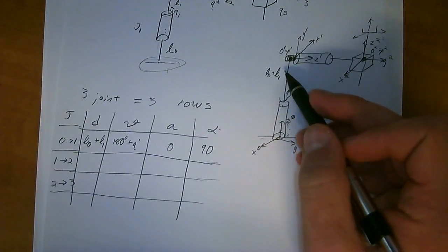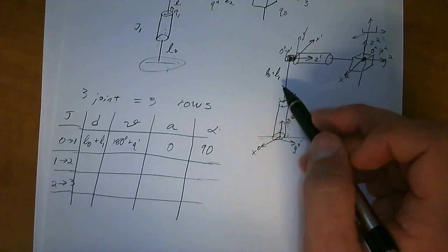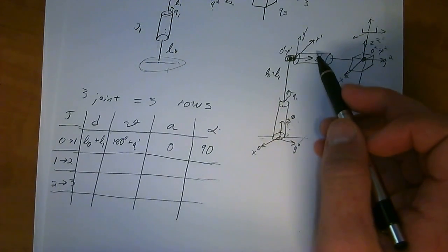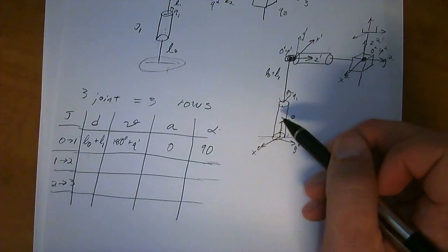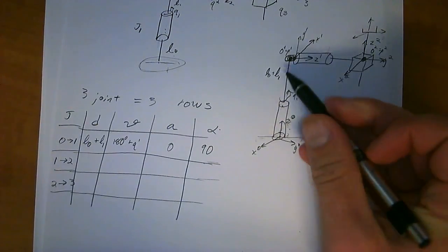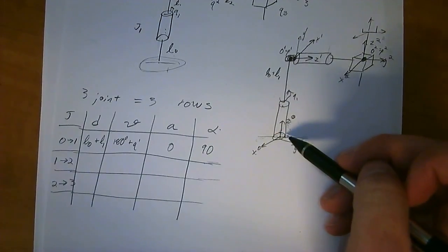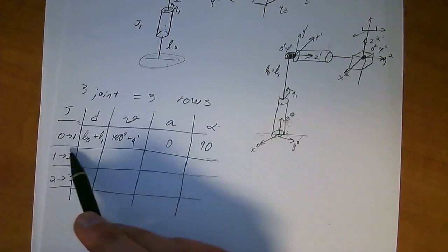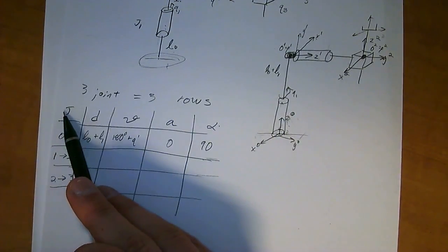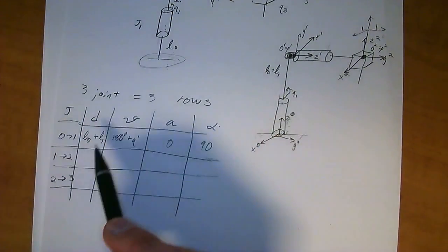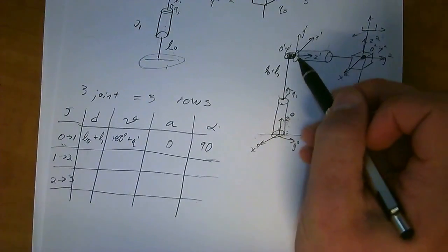We can include this joint in the application. Whereas in the previous forward kinematics that you may have learned, you usually do the second joint in the sequence. Like you go from here to here in the old style, but with DH you go from the bottom of this joint to the beginning of the next joint, and you only consider the very first joint in that sequence. So that's how to do this. So we are only considering the 0 axis, which is joint 1, for this whole row. And that's what this is useful for.